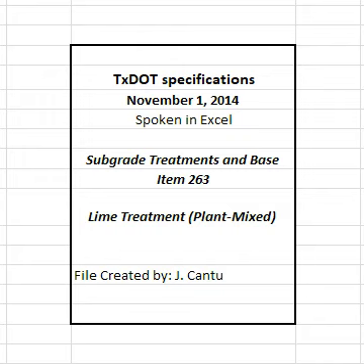2.3 Water. Furnish water free of industrial wastes and other objectionable material. 2.4 Asphalt. Furnish asphalt or emulsion when permitted for curing purposes that meets the requirements of Item 300, asphalts, oils, and emulsions, as shown on the plans or as directed.